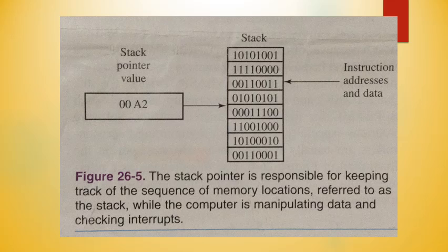Erasable programmable read-only memory, or EPROM, is a special type of PROM that can be reprogrammed many times. When manufactured, a small window is left on the chip. Any program entered into the chip can be erased at a later time by shining an ultraviolet light through the window on the chip. The chip can then be reprogrammed using a programming device.